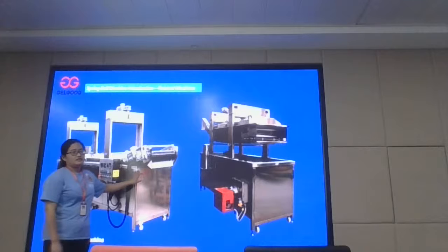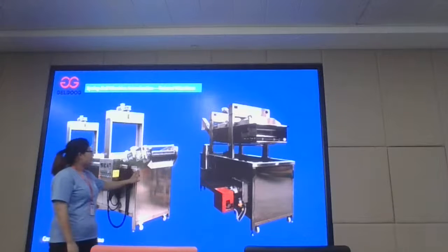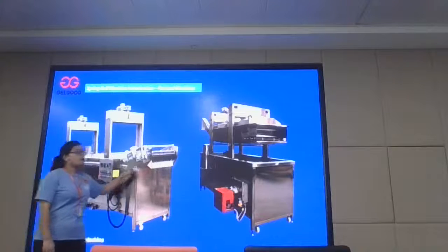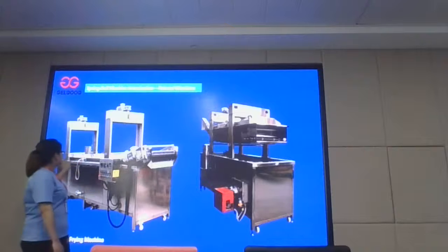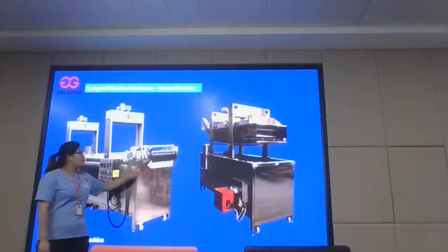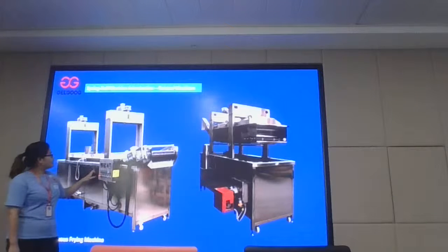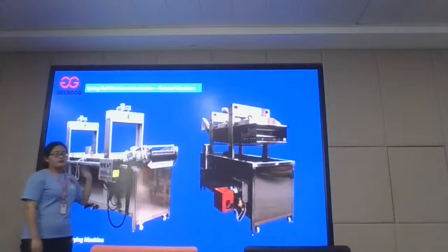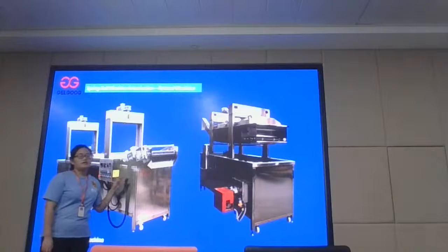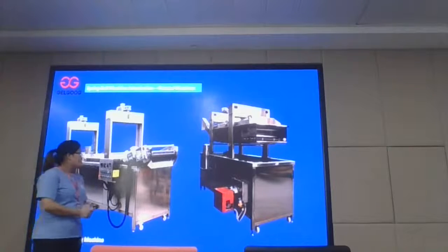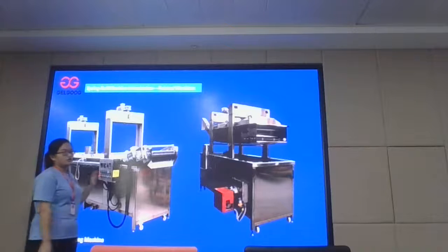The inside of this continuous fryer machine is the belt. The belt speed can also be controlled. Through controlling this belt moving speed, we can control the whole heating time, and besides the frying speed, we can also control the heating temperature. Because different materials may have different heating temperatures, we can adjust the heating temperature according to your requirements through the control cabinet.